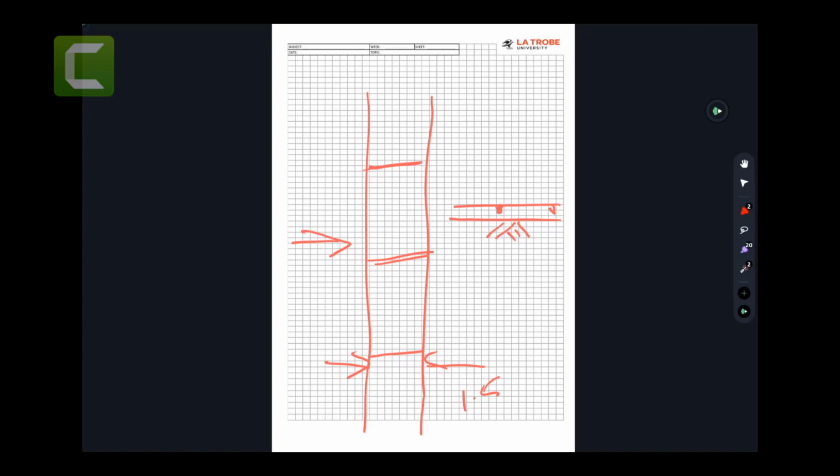However, if you've got a long footpath, you don't need to do that, because it's still going to look too busy and ugly, and again, cost time. So usually you can go to a 1:2 ratio. Someone will tell me, but isn't this also going to cause shrinkage? That can be managed by putting in some steel. As we're going to see in the examples for shrinkage, steel can resist those cracks and prevent them. So this is really how it works.